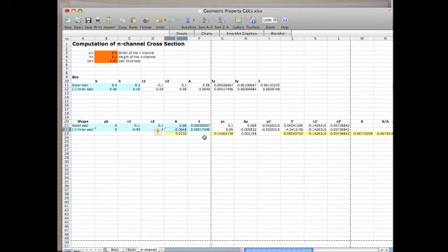Now, okay, so what are we left with? It goes through, again, here's the location of the centroid of the sections. This is the outer section, 0.1 meters, that's half the height, and 0.09 meters. This is the product of the area times the YC. Here's the sum of those. So that's the numerator of the equation for finding the CG. And so here, all we're doing is taking that numerator and dividing by the total area. And that gives me the location of the centroid.